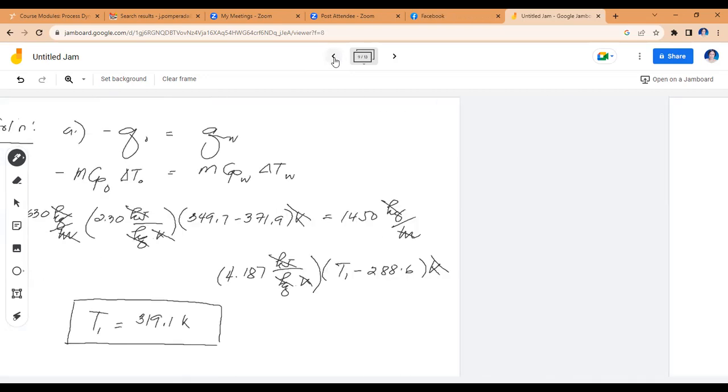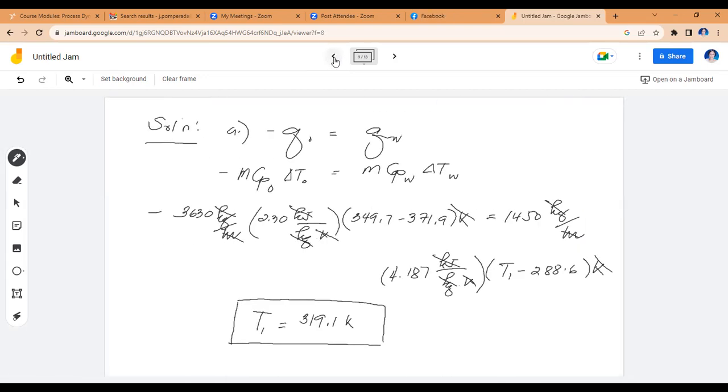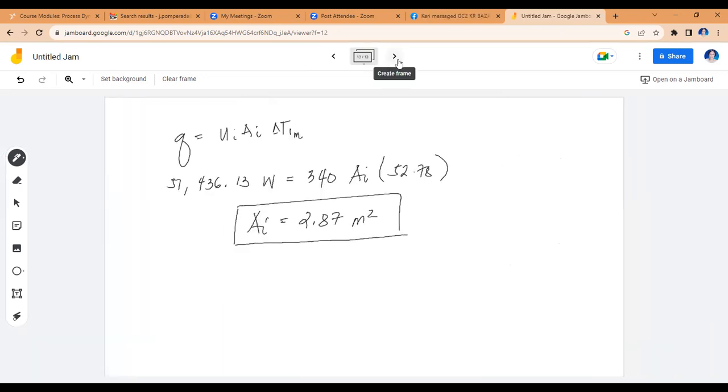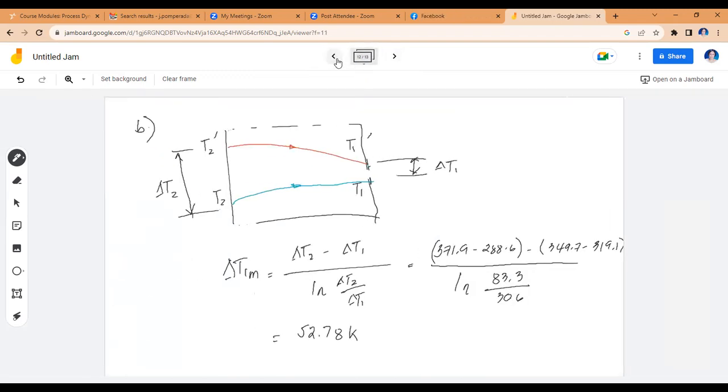Now, will our T sub 1, that's the outlet temperature of your cooling water, be affected by the flow? No, correct. It will not be affected because the formula in determining the outlet temperature of water is based on this fundamental concept of heat transfer: one material loses heat, another one gains heat. So it's not dependent on the log mean temperature difference. So the same T sub 1, or the same outlet temperature of water. We have noticed that there's a change in the inside area between co-current and parallel flow.